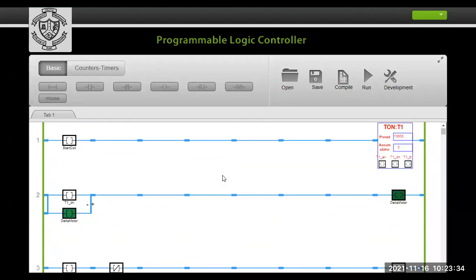Okay, so in this way, in industry where 5 HP motors are running, because it consumes huge current whenever it is starting. I think you all know this. Whenever any experiment is going on, when it starts, within 1 minute, maybe its rated current is 2 ampere, but it is drawing 5 ampere. But after a few seconds, not 1 minute, very few seconds, say 30 seconds, it will come down to 1 to 2 ampere.